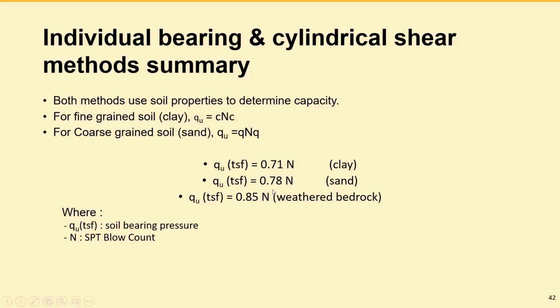For sand, it is 0.78 multiplied by N. And for weathered bedrock, it is 0.85 multiplied by N. So you can see, this is the soil bearing capacity. If you have the SPT blow count, you can come up with the soil bearing capacity and just multiply it by the helix configuration, the helix area, and you get your ultimate pile capacity.